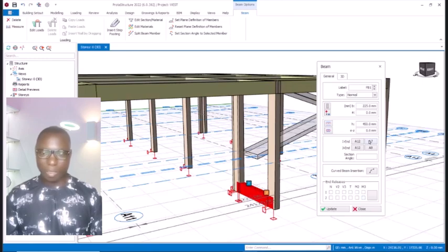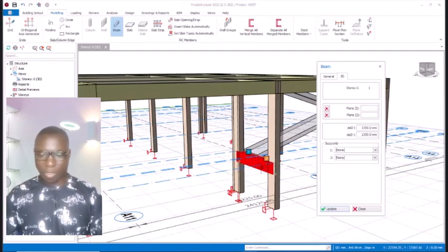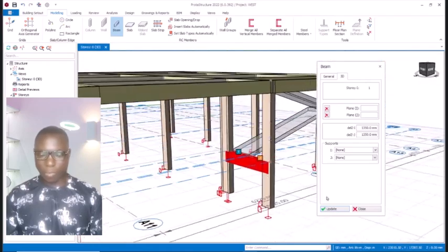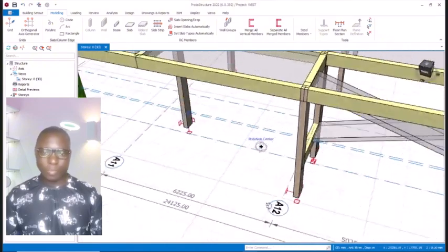So having the beam selected, come to the provisions, and then you see these elevations where we have it to be 1350, just like this, in both I and J end of the beam successfully. Click on the update. See, beam goes up just like this. Click on the OK options, so you can see what we are having.